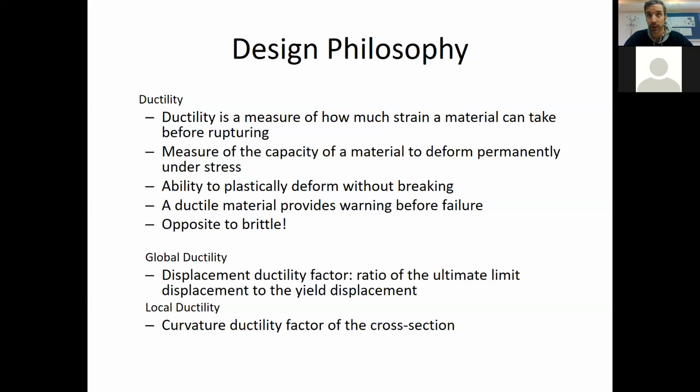This deformation is often kind of fatal, so it's an ultimate limit state condition. So your structure after the earthquake will be useless because of all the deformation induced, but at least it will not collapse and it will not kill anybody. So it is better to need to rebuild your structure than on top of having to rebuild it, also having killed a few hundred people. But that's why this ductility philosophy has started to win today.